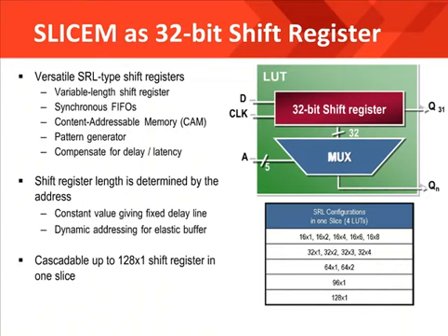And of course that will be a big waste if you're building a large component and expecting the shift register LUT to be used. The benefit of this resource is that it can effectively provide the work of 32 registers with a single lookup table. And in pipelined applications, that is a huge savings.